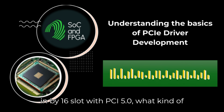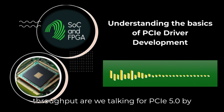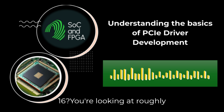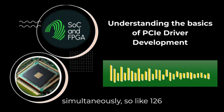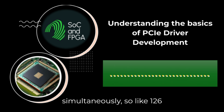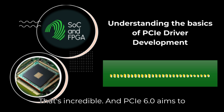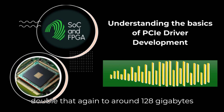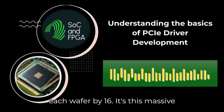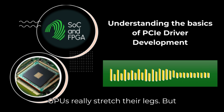Wow. So for an x16 slot with PCIe 5.0, what kind of throughput are we talking? For PCIe 5.0 x16, you're looking at roughly 63 GB/s in each direction simultaneously. So like 126 GB/s total bidirectional bandwidth. That's incredible. And PCIe 6.0 aims to double that again to around 128 GB/s each way for x16. It's this massive bandwidth that lets the newest SSDs and GPUs really stretch their legs.